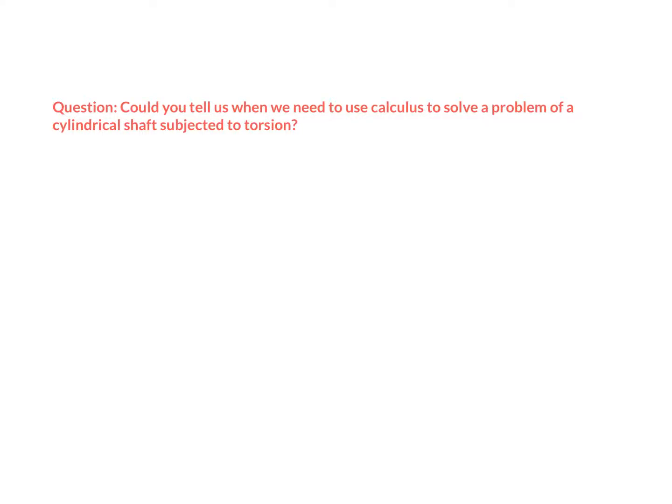The question is, could you tell us when we need to use calculus to solve a problem of a cylindrical shaft subjected to torsion? Yes, there are problems where the key quantities, including the internal torque T, the radius of the shaft R, and the relevant material property, the shear modulus, vary with distance x. In these cases, we will find that the formulas we have used so far are not strictly valid.